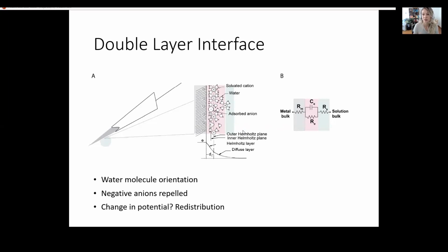Now, this is a capacitor, right? And we said before that the amount of charge that a capacitor can separate depends on the voltage difference between the plates. You cannot only change charge on one side of the capacitor. They are so intimately linked that if you change the potential here and the charge distribution here, you're changing the electric potential difference across the plates. We said before that the amount of charge it can separate is proportional to that voltage.